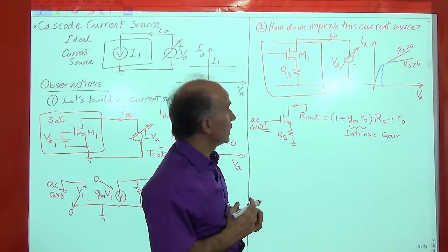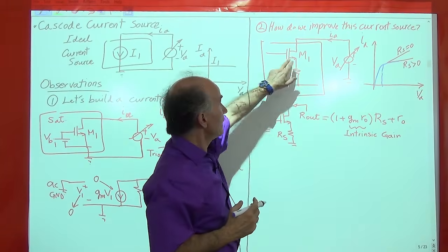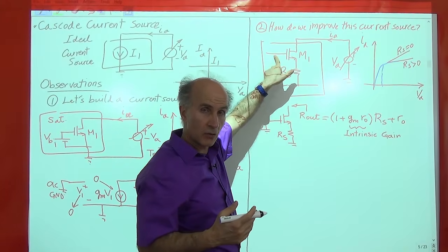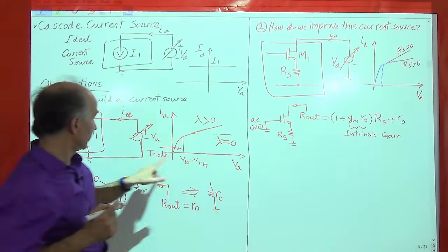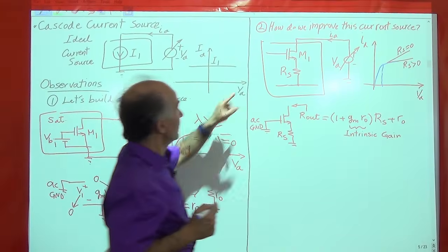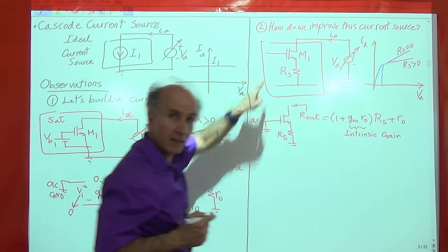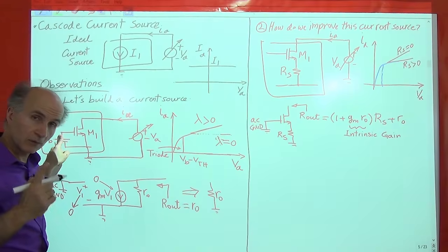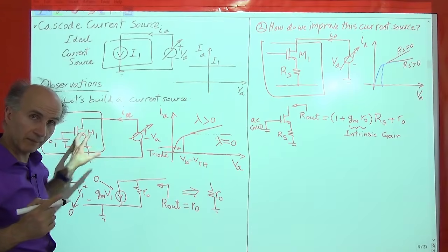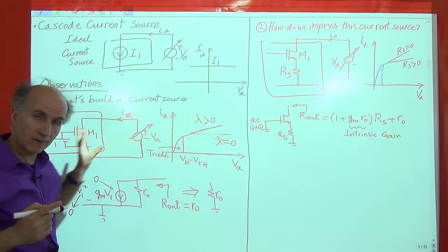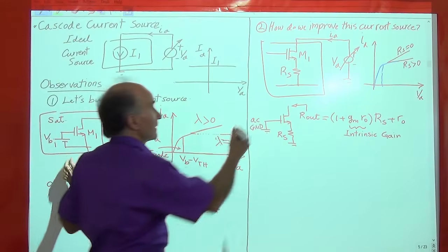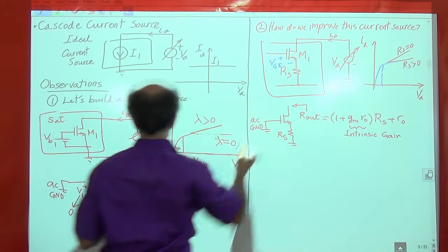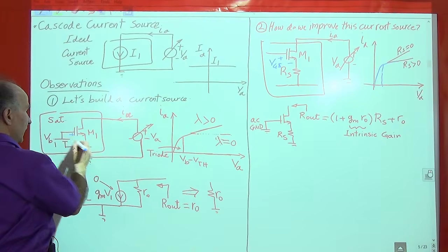Okay, well, what we know is that a MOSFET begins to go into the triode region when its drain is below its gate voltage by one threshold, as we saw here, right? One threshold below. So the question is, is this gate voltage the same as this gate voltage in the previous case without degeneration or not? Let's assume that the bias current that we have is the same. And let's assume that the transistor dimensions are the same. So that means that this VGS has to be the same as this VGS, right? Because they have the same current and they have the same dimensions.